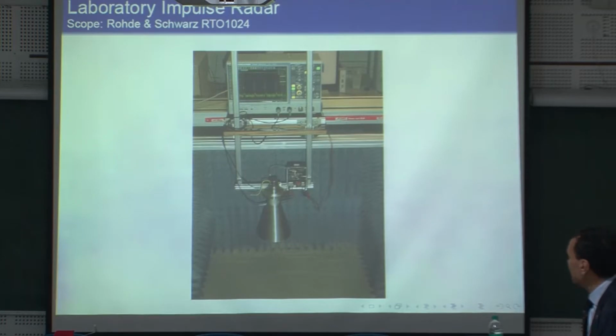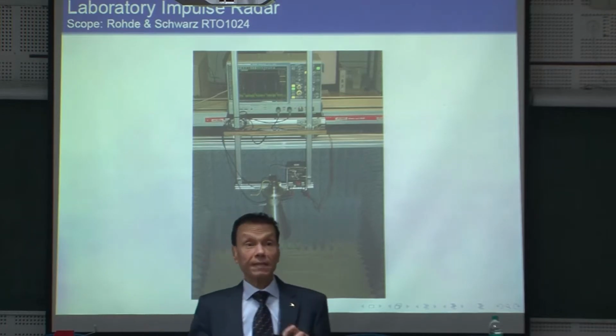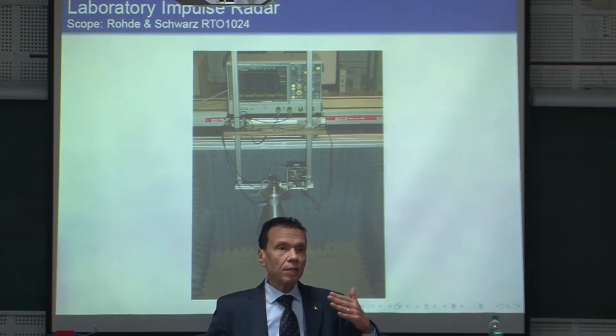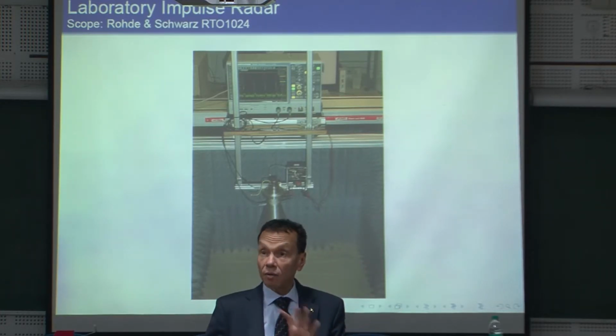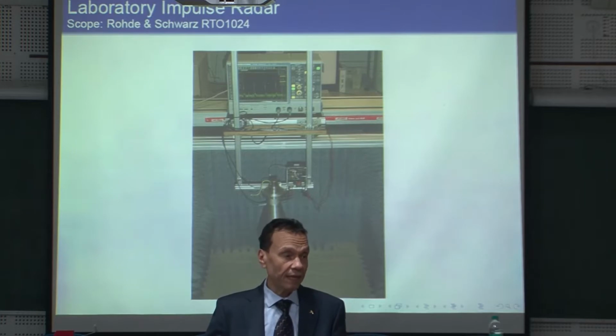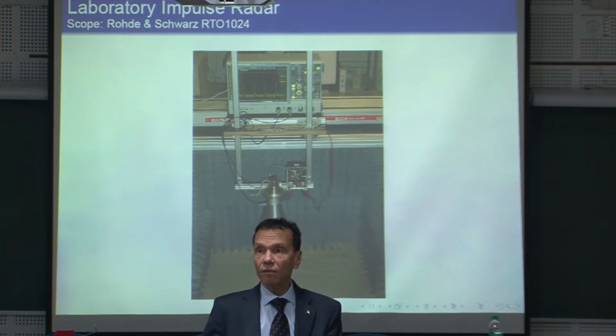I think this is here dedicated to another network analyzer, Rohde and Schwarz. I remember that this one here was very, very low frequency. It is up to 4 gigahertz because we don't have another one. This is a 4 gigahertz. This is just for what I told you last time, or maybe 2 days ago, about the penetrability. Because if you go higher with the frequency, with 40 giga and so on, you can achieve limited penetrability. Although the fractional bandwidth is high, and you can have nice resolution, you cannot penetrate into the ground for long distance.